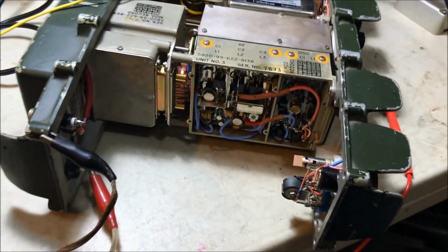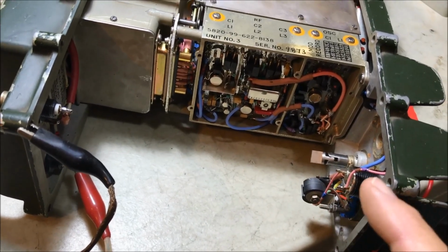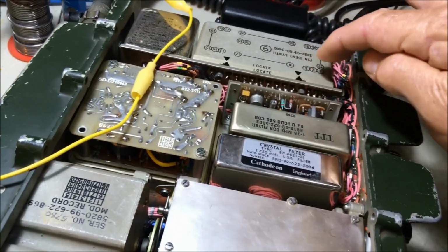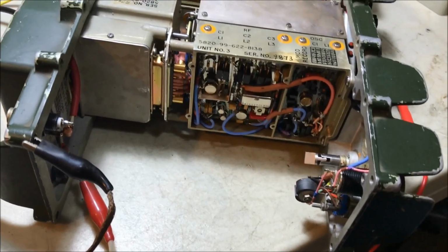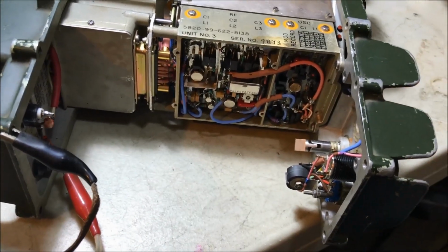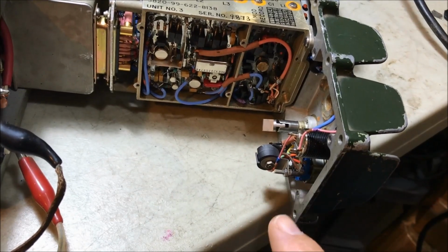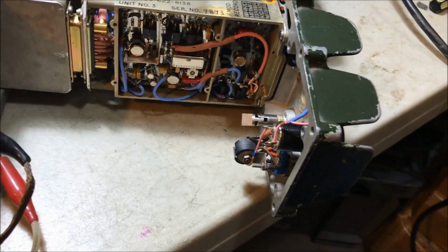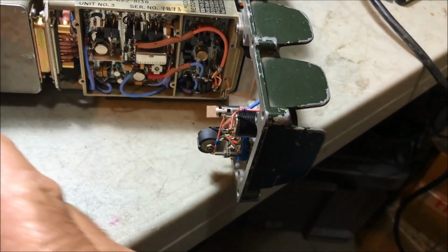Okay, on this particular radio here, I've already removed the tuning section. Really not necessary. We could be taking this DC reading from behind the synthesizer when we get it off, but because I've got this particular radio stripped down to this stage, why not take it here? If you wanted to remove the tuning section, it's really easy. There's just 4 screws, 1 wire to unsolder, a nut to come off, and a little knob at the front, and the whole thing comes off.